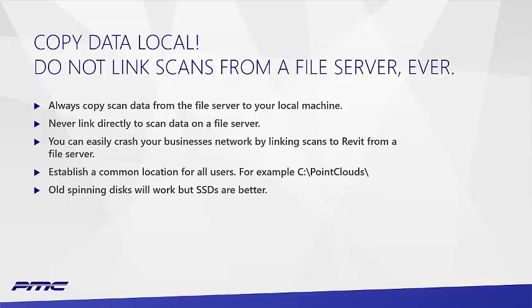This is kind of counterintuitive because for years I think a lot of us have been told never work from your local machine, store all your data on the servers, et cetera, et cetera. That's correct for CAD files. When you're talking point clouds, that's really not what you want to do. And not only that, you're likely to get a visit from your IT folks wondering why you're crashing their network by trying to stream gigabytes of data off of a server share.